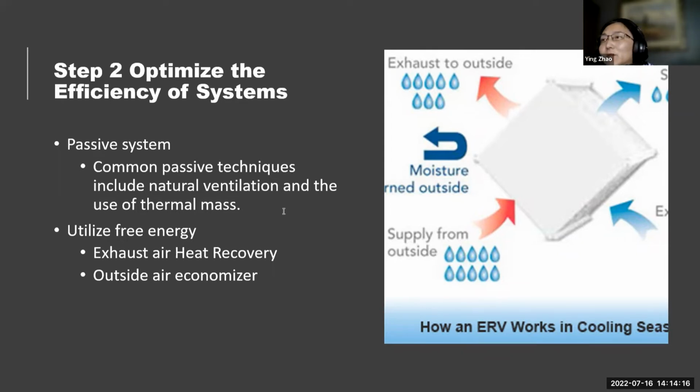Next question. Across thermal modeling and passive design, increasing thermal mass to enhance heating, cooling, ventilation in a building interior. Is this applicable in all zones? Oh yes, we talked about that. It's better for the climate with a big temperature difference between day and night. So it's good for a lot of climates, except for hot and humid that has a low temperature difference.